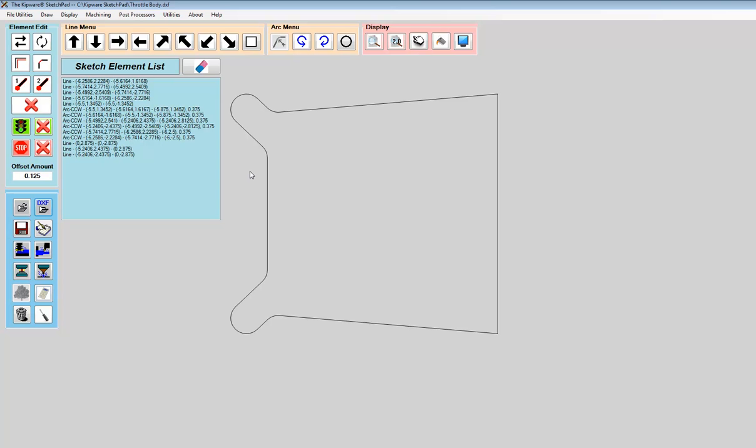And sometimes if you create a drawing and use blocks, or if you use polylines, you need to use the explode feature in your CAD program that will take those blocks of elements and make them into individual elements. So before you export the Dxf file, you should use the explode feature in your CAD program to make sure that you have individual elements.